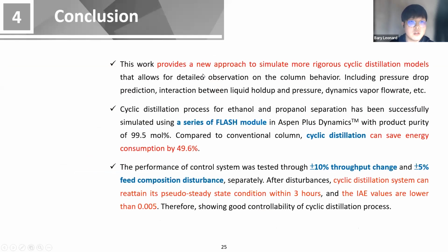So in conclusion, this work provides a new approach to simulate more rigorous cyclic distillation that allows for detailed observation on the column behavior, including the prediction for interaction between the liquid holdup, pressure, and dynamic flow rate, and also pressure drop. The cyclic distillation process for ethanol propanol has been successfully simulated using the flash module in Aspen Plus Dynamics, and